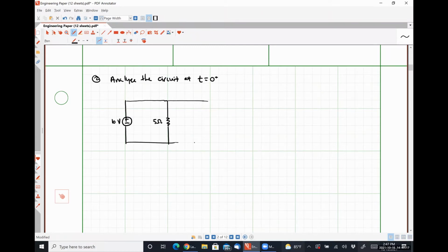It happens a bit. So let's talk about what's going to happen with our capacitor here, because I don't think we talked about this much on Wednesday. We know that the voltage drop across the capacitor cannot change abruptly, right? So our voltage drop at t is equal to 0 plus has to be what? 0 volts. Sorry. VC at 0 plus has to be 0 volts.